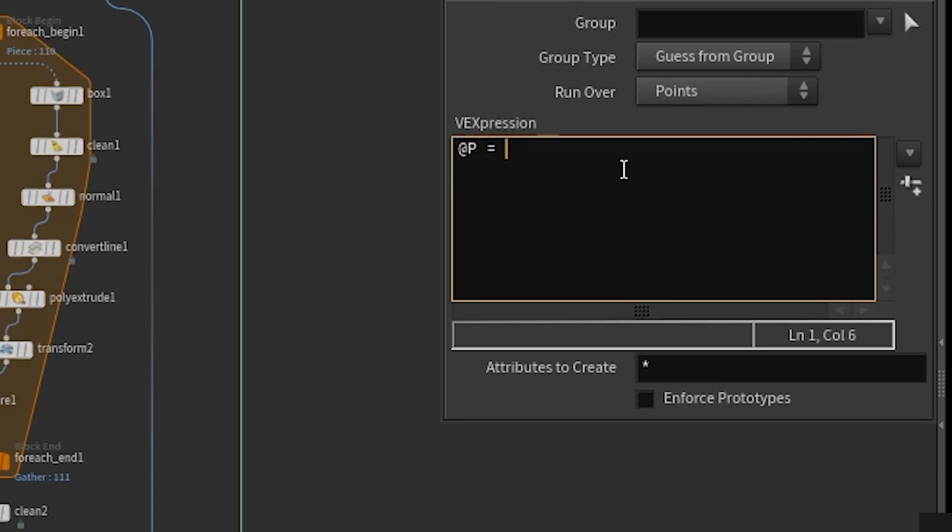So we can do that with the help of the uvsample function. It takes the second input, 1 is for the second input, 0 is for the first one, saying which input we need to get the attribute from, and pointing to the attribute by which we are going to get the position. In our case it's UV. And we need to point to the UV coordinate. In our case it's position now.